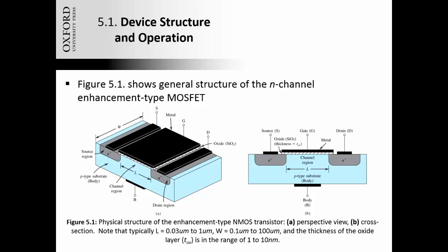the depletion mode. Essentially, I'll just tell you, enhancement mode means that the channel that will provide the conductivity between the drain and the source is not initially present when the device is not powered, or when the gate does not have a voltage applied to it. You must enhance its conductivity by applying an electric field or potential between the gate and the source.